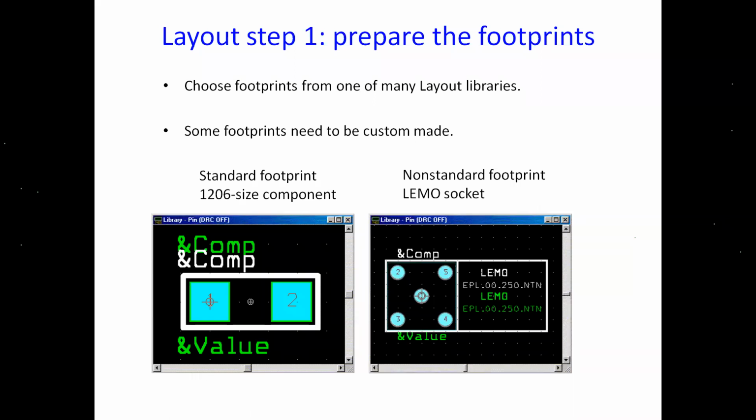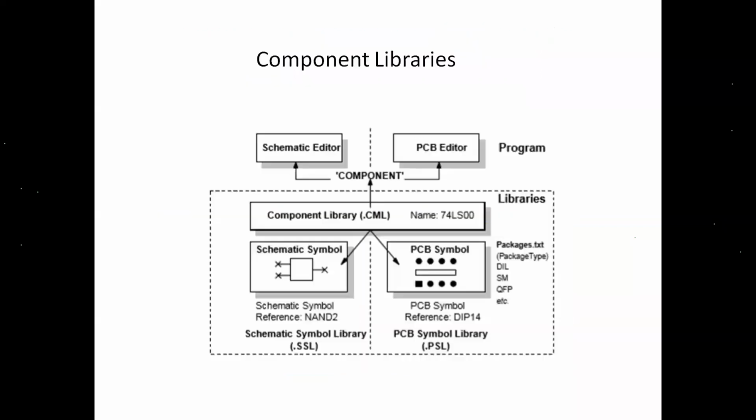For that you need to access the complete information about the component detail, like component data, the component manufacturer's data sheet. From there you can get different kinds of information, like component size, shape, height, and volume, everything. Based on this, you can clearly create the footprints.